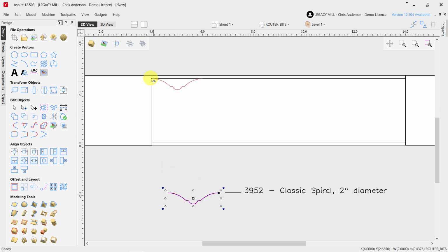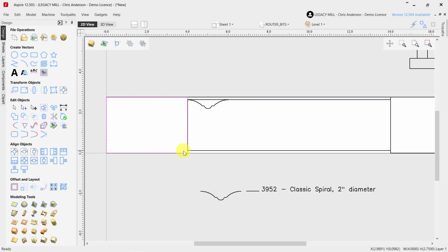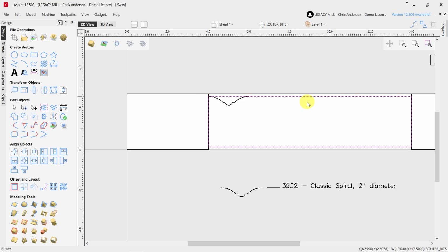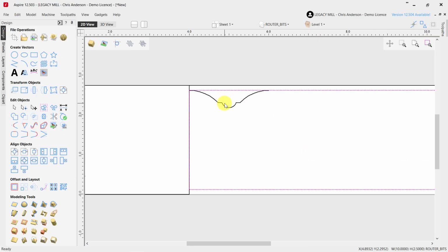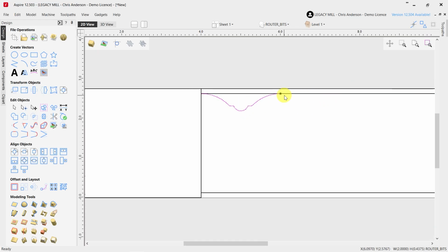If we place this, remember that this section here on the end represents a square section. Same with this end here is a square section, but this middle section represents a round section that's been turned round to 2.5 inches already. Okay, so we're applying a detail to this round surface. So by placing this here along that face, what we've done is we've taken the entire shape of the cutter and put it within the surface of that diameter. Okay, so we're getting the entire shape.